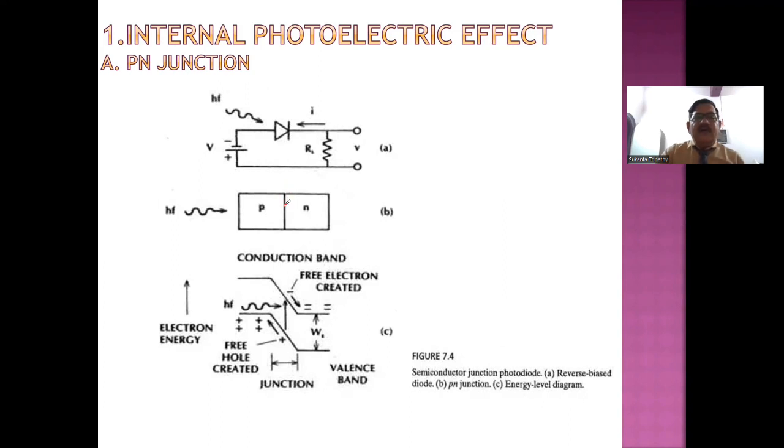But when these 100 electrons which are produced are separated by this reverse bias voltage, they will flow along this path, that means along this material medium, and therefore some of the electrons will be absorbed. So you may get here 80 electrons or 75 electrons rather than the 100 electrons which you are producing here due to this light which you have incident here. Therefore, the efficiency of this detection has decreased.